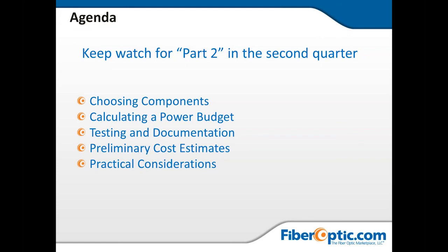It also has a couple of extra properties in that it reduces the effects of polarization modal dispersion, which we're not digging too hard into dispersion in this particular venue. There's other webinars that I do that will talk about that in greater detail. Again, check back into the archives or look for future webinars revisiting some of those topics. But the NZDS or the newer glass does tend to tighten up on the tolerances for core geometry fluctuations and keeps the effects of polarization mode dispersion lower. So I think that answers that question.